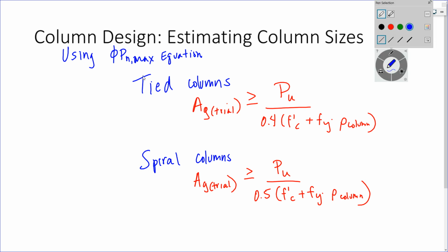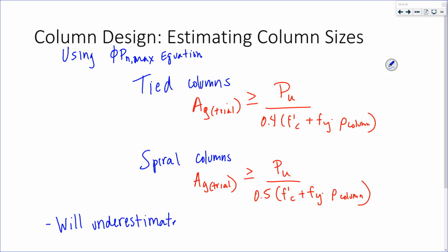Now, right, we're only looking at your axial load. So it will underestimate your size for columns subjected to high bending.